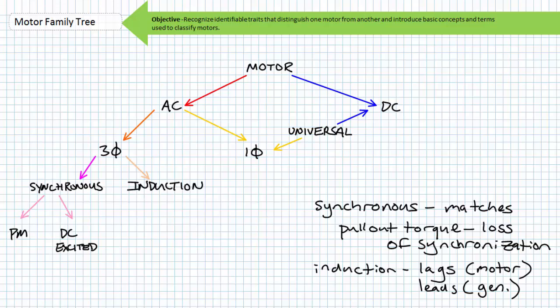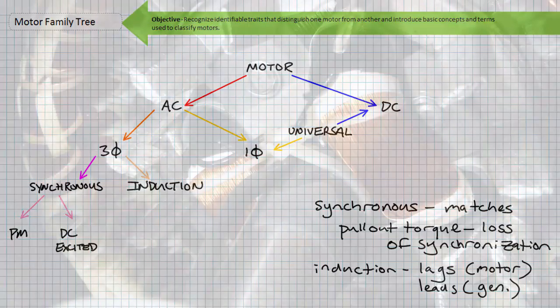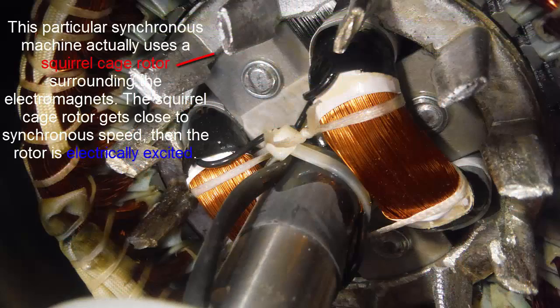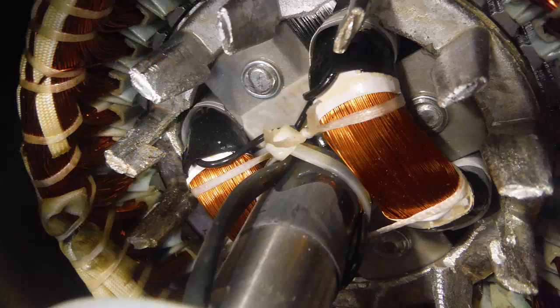Perhaps the rotating magnetic field of a synchronous motor could be slowly accelerated using a variable frequency drive, or maybe the rotor could accelerate itself to something very close to synchronous speed via other means before the electromagnets on the rotor are excited. We'll deal with these characteristics in later lectures, but realize that the desirable stable speed characteristics of a synchronous motor come at a price of slightly more complicated means of starting.